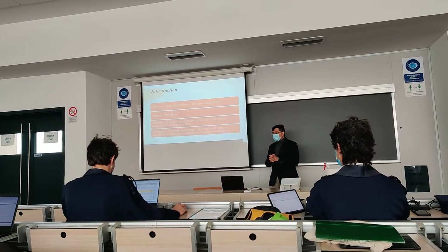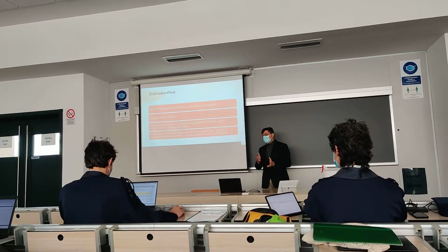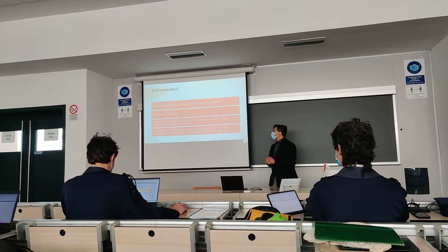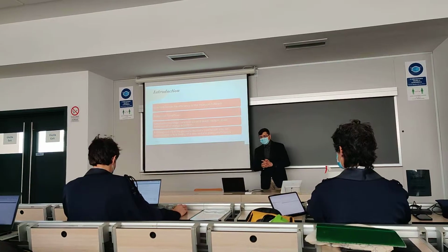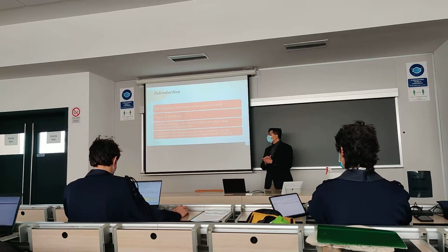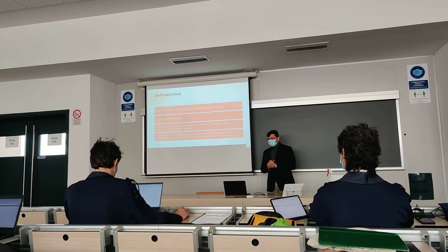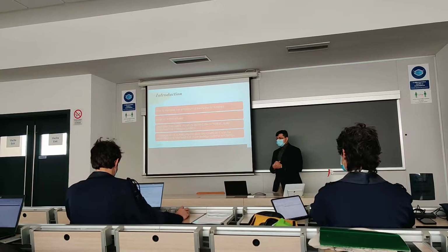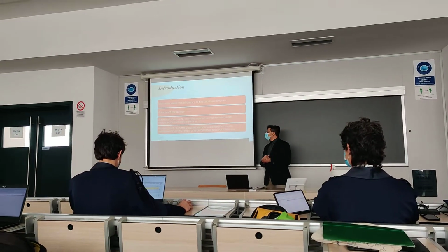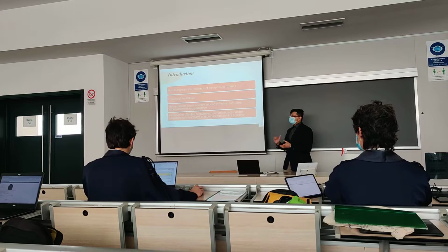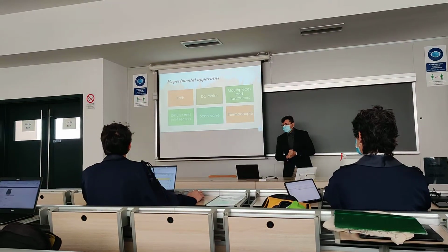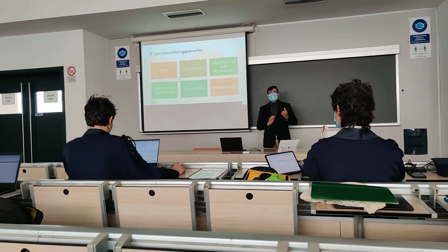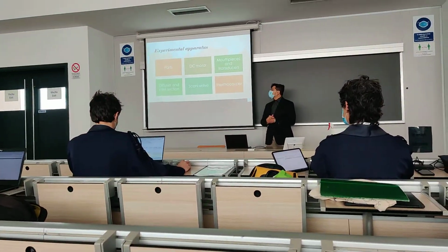As you all know, the major principles behind these turbo machines are Newton's second law of motion and the Euler turbo machine energy equation. It is very important that even a change of 1% of pressure recovery coefficient can be equivalent to 1/10 of a percentage of efficiency improvement. So we are concentrating majorly on the pressure recovery coefficient. Then a brief description about the experimental apparatus which is in the turbo machine lab.